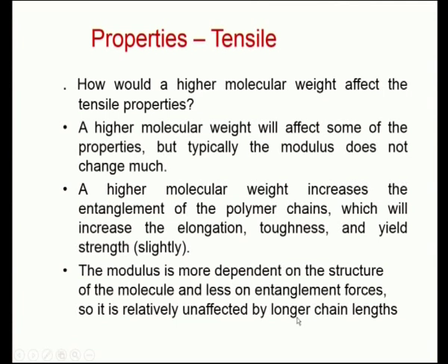So chain length will not have any effect on the modulus, rather the modulus will depend more on the structure. So the presence of bulky groups, for example polystyrene, where you have benzene as a pendant side group. So polystyrene has a very high tensile modulus.